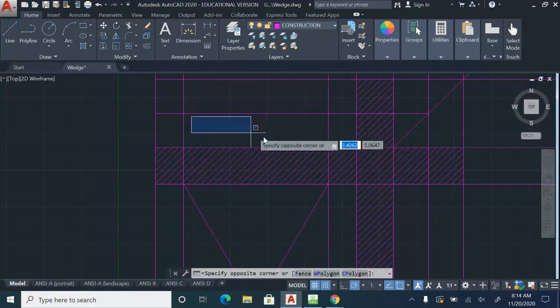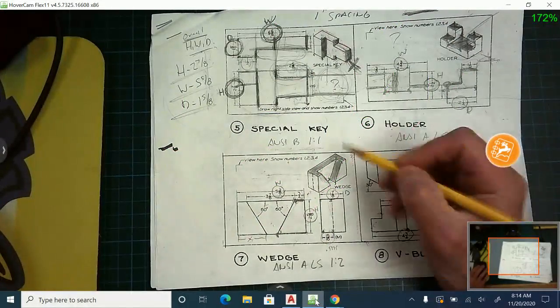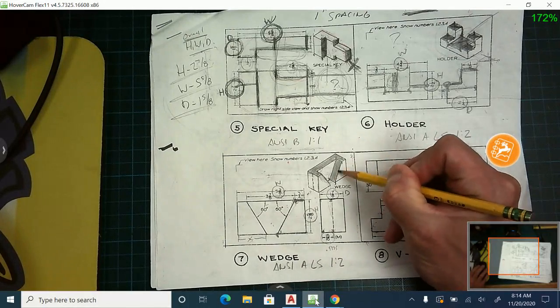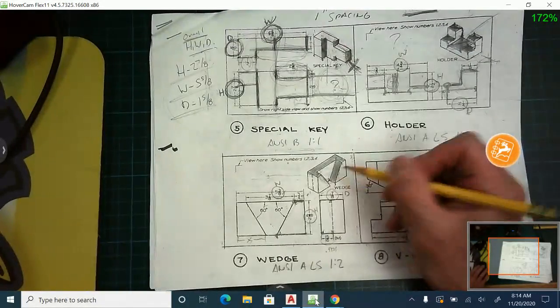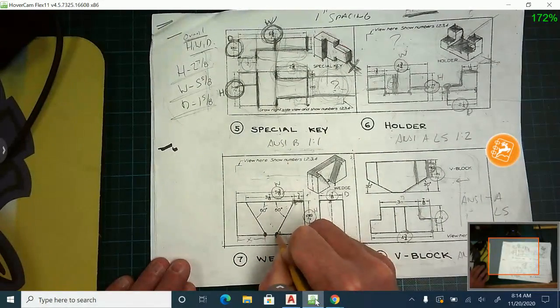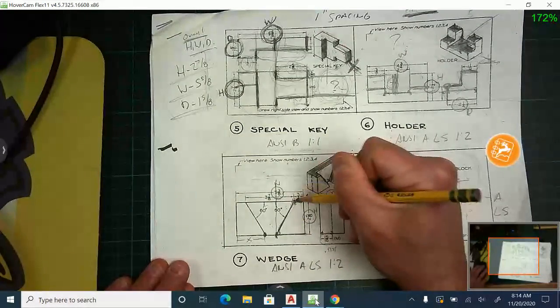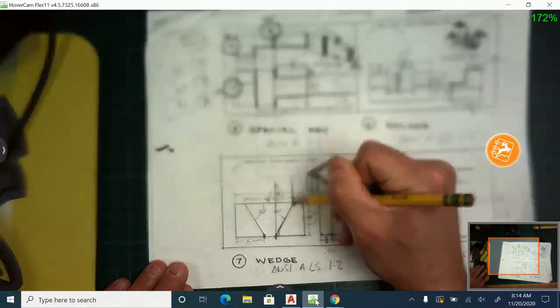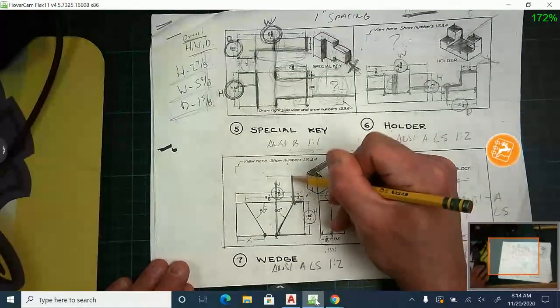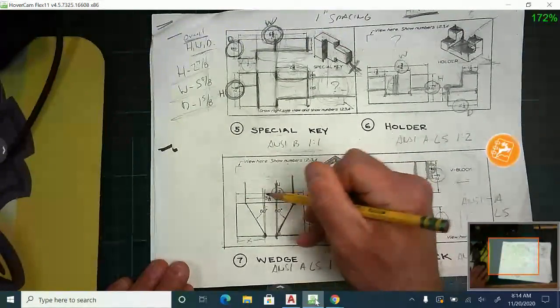Now the angles would be in this area here. If we look at it on the plans here, you would see like a little box shape looking down on it on both sides. What you need to project up now is this point and this point, because we're seeing this angled surface, but we're seeing it in the top view. So those are the 2 points we want to offset up. Now we already have the 3/4 one. So to this point, these 2 lines need to come up.